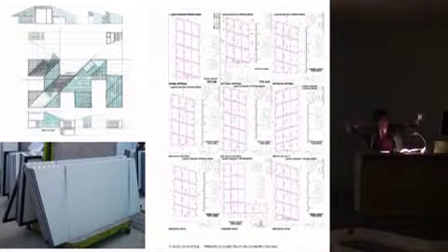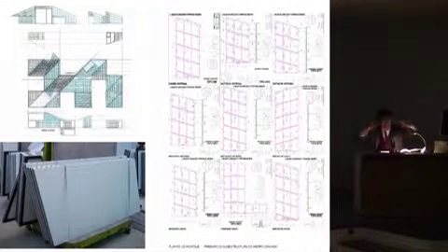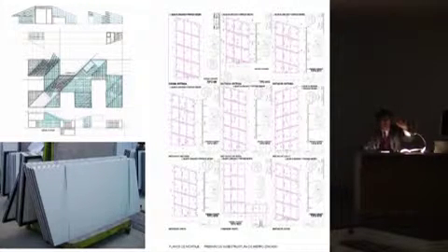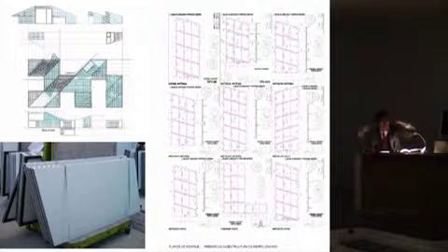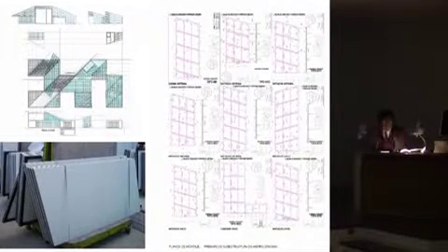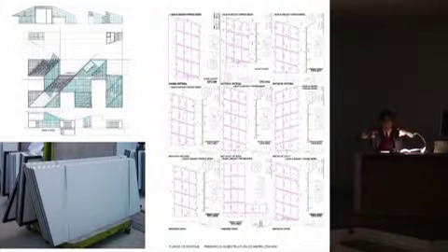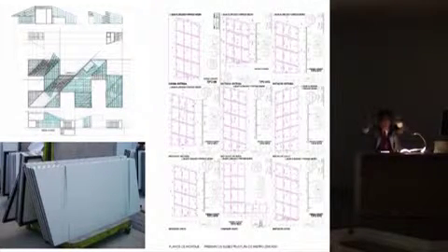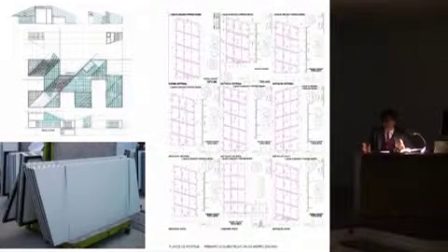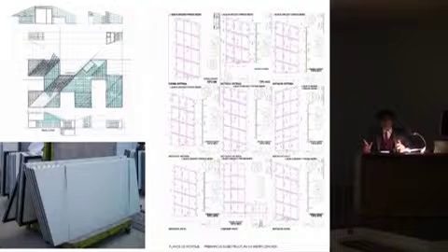So you prepare based on the concrete structure, and you see the inside with the impermeabilization and the stainless fence, 4x4, no, 5x5 with the injected isolation. Those tubes have some hooks, and on top of them, with the right geometry, you clip all the panels, 3x1, 6 millimeters, that are relatively light.